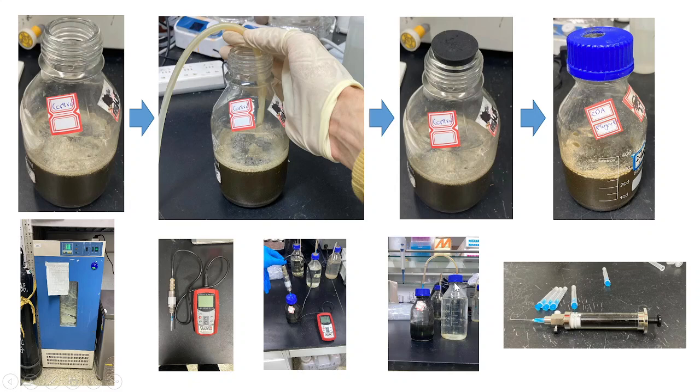And you can see that this pipe is inserted in the water in this way. When the biogas is removed or exhausted from this headspace, it will not let oxygen get back inside this digester. That's why it is essential to design such bottles carefully. It should be immersed in water so as not to let the oxygen go inside your digester and affect the anaerobic condition.